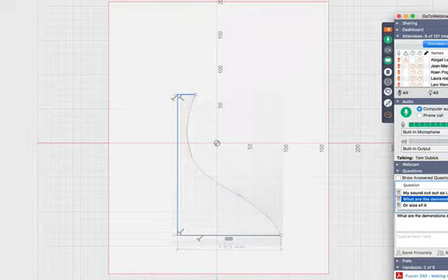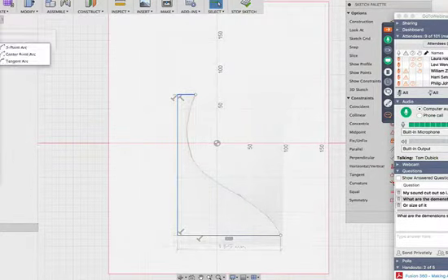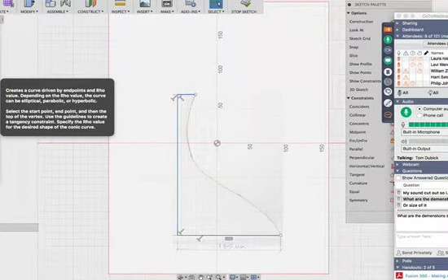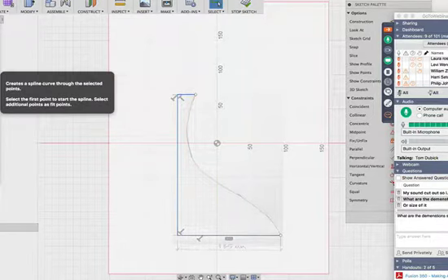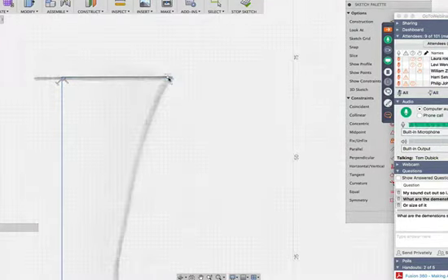All right. Come on, Harry, let us know. Okay, Philip, okay, great. So let's do this next part. We're now going to go to sketch again, and we're not going to use the straight line because we're going to curve. You could try to do curves, but really we're going to do what's called a spline. This is a lot like nodes in Inkscape. So I'm going to go over here. I'm going to make sure I start at the same place. There's a little rectangle. And I'm going to work my way down.